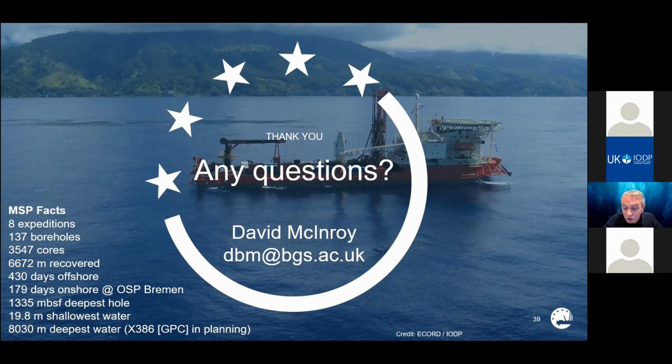I don't know if there are other modular platform manufacturers out there that might. You're probably starting to look at a bigger vessel to hold those longer legs to get those deeper water depths, so I think it would be unlikely that a combi float type modular platform would get there. If you're going to target the 55 to 90 meter range, you're looking at either a lift boat, and then you have to accept the limitations that come with that, or a geotechnical rig, in which case you have to use heave compensated wireline drilling. So there are some trade-offs in that 55 to 90 meter water depth range.